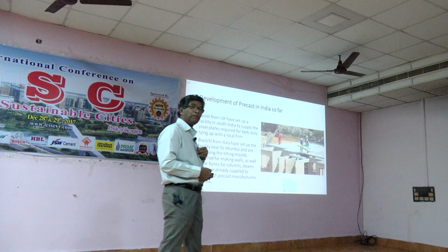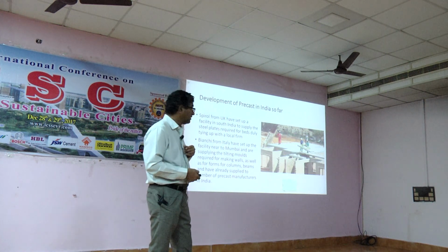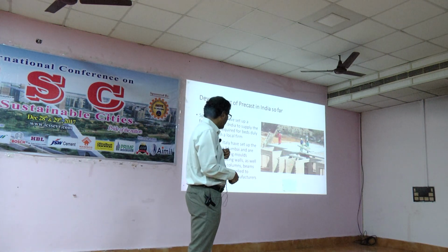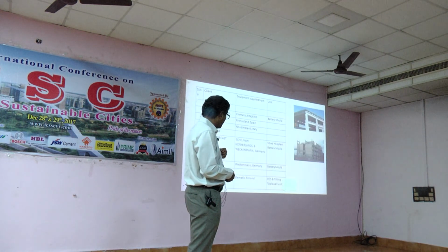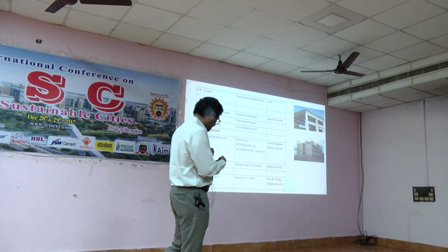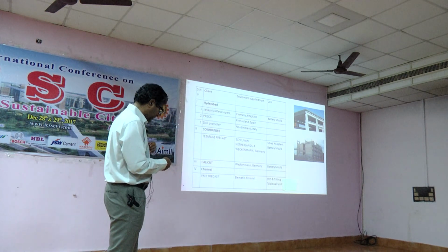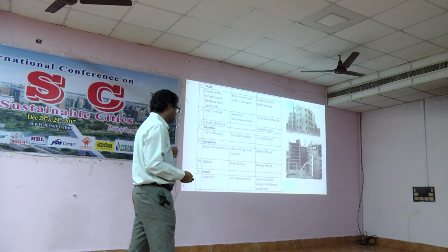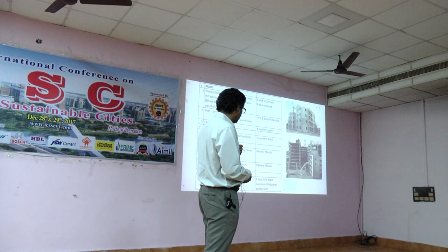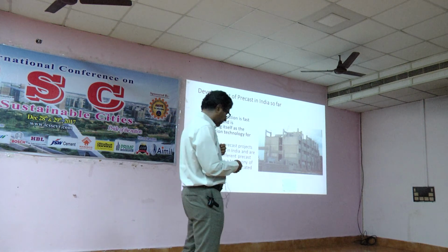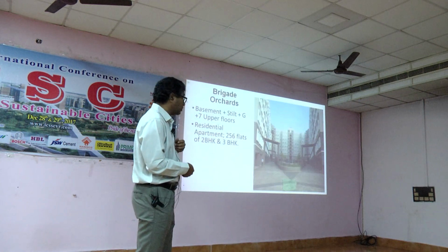And then precast slabs are 1.2 meter wide, hollow core. They can be put on the brick walls or on the columns wherever you want, and the floor slab is done in one day, very simply. So many companies have already come into India, and they are coming day by day. Even in Vijayawada, now we are going to get about 4 factories where we have been motivating the guys to set up, and government is also thinking in terms of precast is the only mode to construct the building.